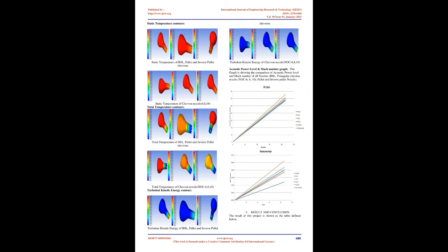3. Nozzle configuration. In this portion we calculated dimensional parameters like length of nozzle, inlet and exhaust diameter of nozzle, number of chevrons, and length of chevron for the design of the baseline and chevron nozzle. Simple triangular chevrons are used for the present configuration study. The geometry of a chevron nozzle is defined by parameters such as number of chevrons, n, length of chevron, l, tip angle, ss, and penetration angle, a. The figure represents a simple schematic of the chevron geometry with its shape-defining parameters.